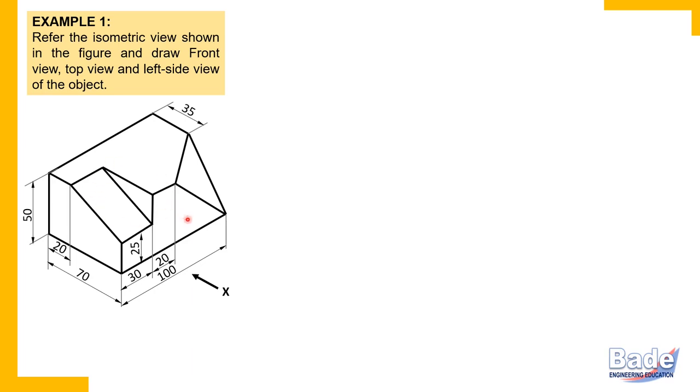These are different surfaces. Now when such a body or a three-dimensional diagram is in front of you, what should be your approach? As I told you, basic approach remains the same. Now here, first thing what you are going to do is check overall length, width and height of the object. Now this is very important to understand that length of an object doesn't mean its longest dimension. Remember, length is dimension measured parallel to length axis.